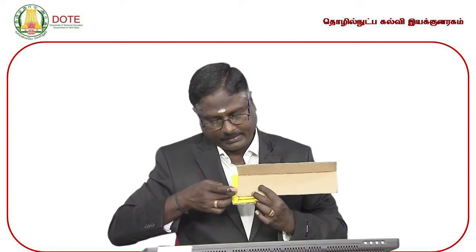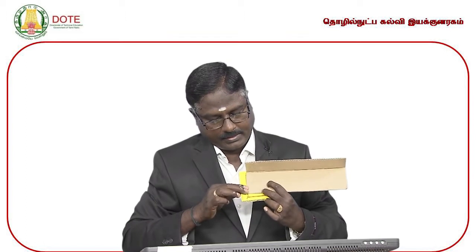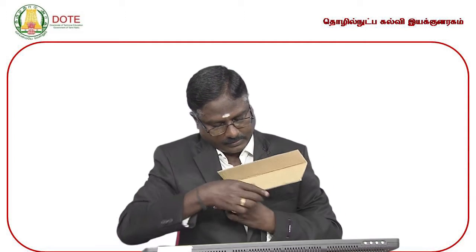This is the arrangement, and this is the angle, the length of the angle, the thickness of the angle, this is the outstanding leg, and this is the connected leg. And if this member, and this is the gusset plate of course, is subjected to a tensile force, a pulling force in this direction, this area of the connection as well as this area, I have denoted as 1, 2 and 3, 4, which will be in shearing plane.